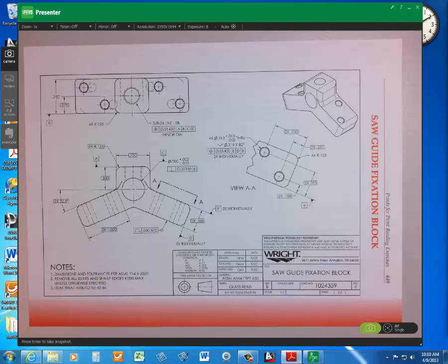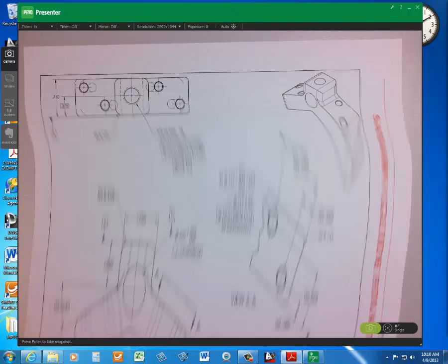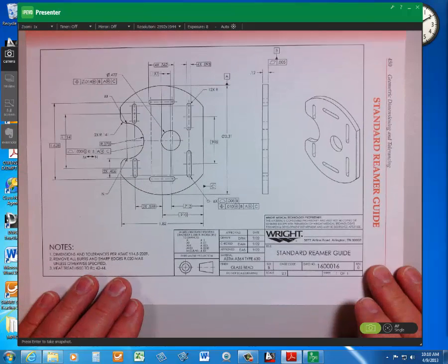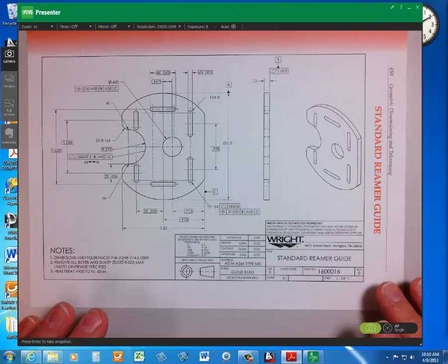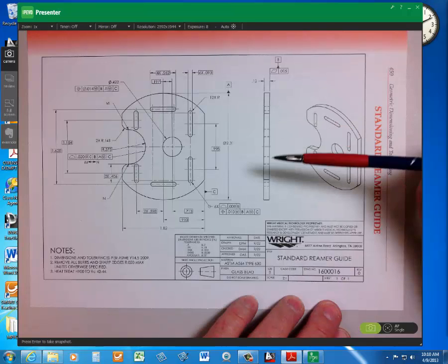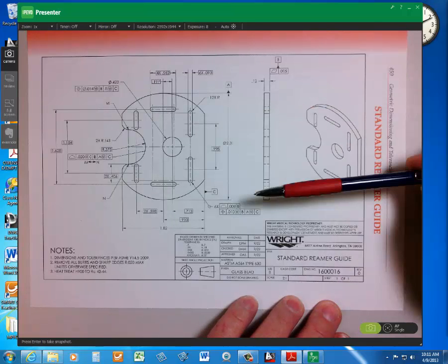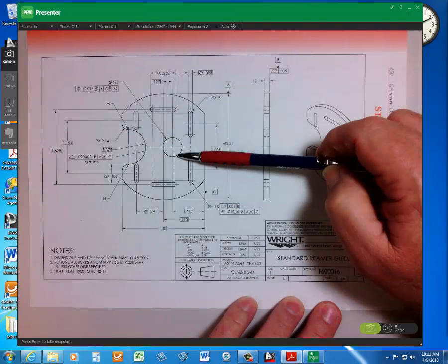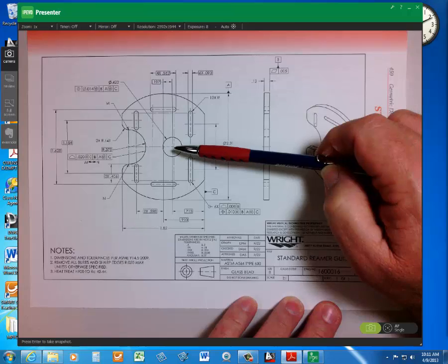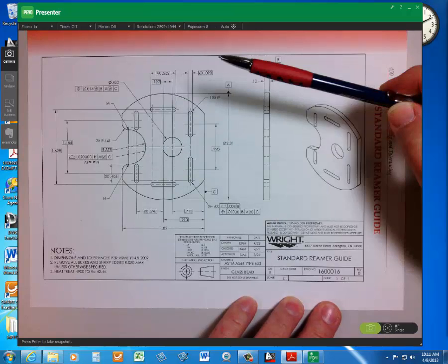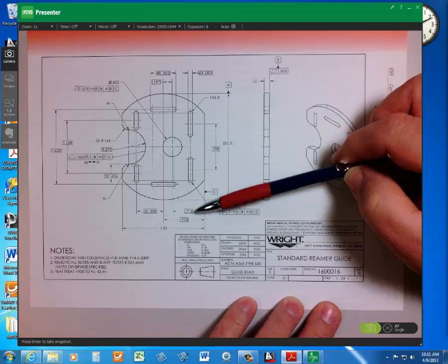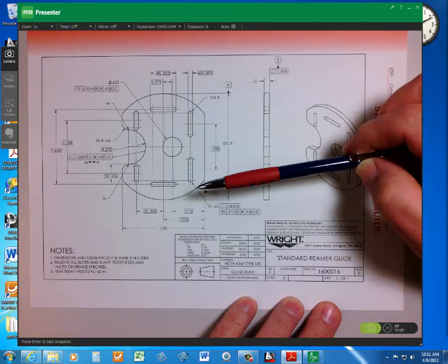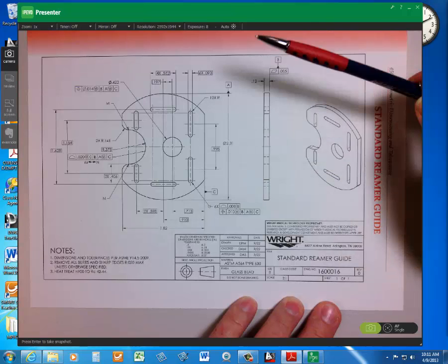Coming in for a landing. 450. 0.422 dimension, diameter dimension. Up here, it's a large hole in the center. Location dimension from datum C is going to be 0.713, and it's on center plane defined by datum A.